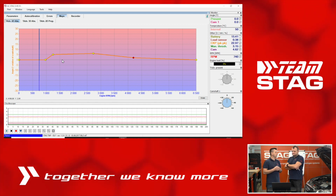just to check the correct information from the gas controller, because it often happens that if you change the ignition angle, you can have the mixture too rich when the car is working on LPG or CNG. Yes, we are reaching better efficiency of burning the mixture in the engine cylinder. That's why the end result of advancing is that the mixture is going too rich.